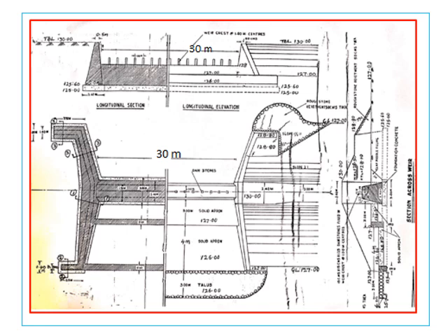You should be able to draw half round sections and half round elevations. Similarly you have to draw a half plan at bottom, a half plan at top, and also the section across the weir. All the levels are decided based on the designs that we have done. These drawings have already been taught in the hydraulic structures design and drawing, so you can reproduce the drawings and fix up the levels that you already decided in the earlier projects. So this is the complete tank project that you have to do. Whatever survey you have done on the site has to be reproduced onto the drawing sheet so that these drawings can be done.